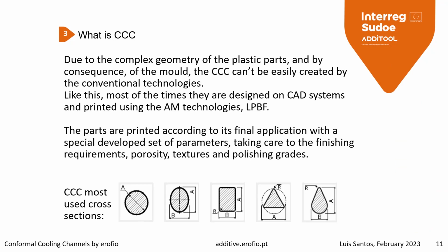Due to the complex geometry of the plastic parts and, by consequence, of the tool inserts, conformal cooling channels most of the time can't be easily created by conventional technologies. So they are designed on CAD systems and printed using additive manufacturing technologies, in our case laser powder bed fusion systems. The parts are printed according to their final application with a specially developed set of parameters, taking care of finishing requirements, porosity, textures, and polishing grades.